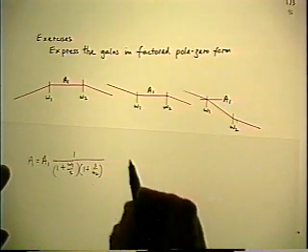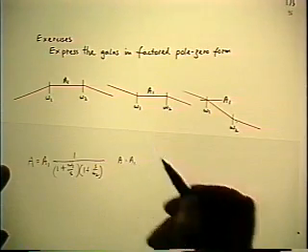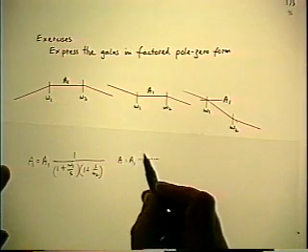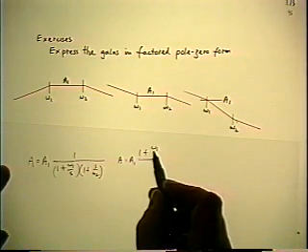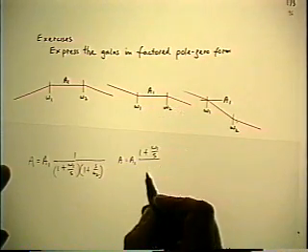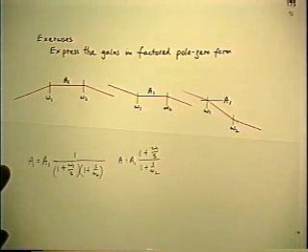Second one, A equals A1, flat gain as reference, look up and down. Look down, you see a concave upwards corner, so that's an inverted zero at omega 1. Look up in frequency, concave downwards, that's a normal pole at omega 2.